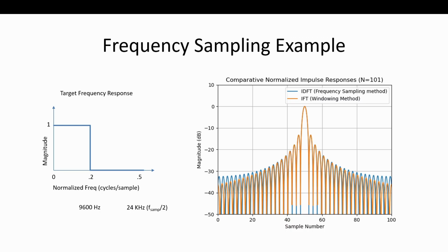Anyone know what that's called? What we would call that? The error that we're seeing, why is the blue higher than the orange? So it's called officially, and it is, time domain alias. If you've been exposed to A to D, D to A conversion, you have aliasing and anti-aliasing. It's the same thing. That happens in frequency. This is happening in time.